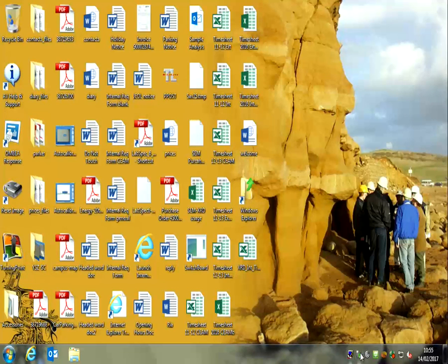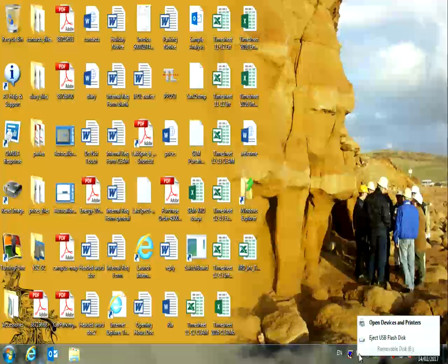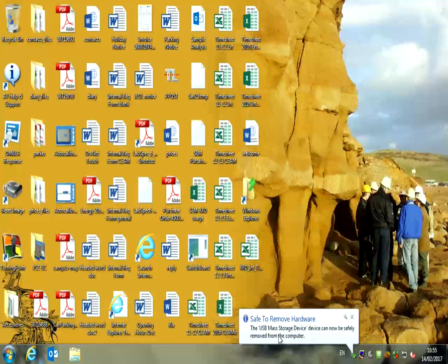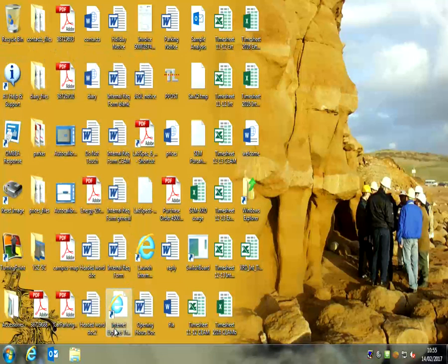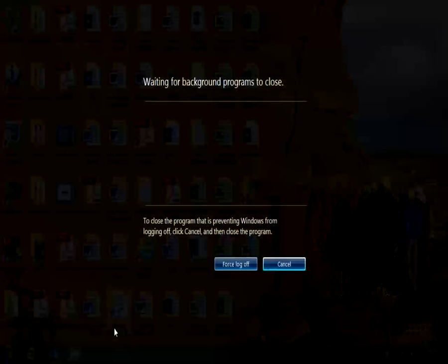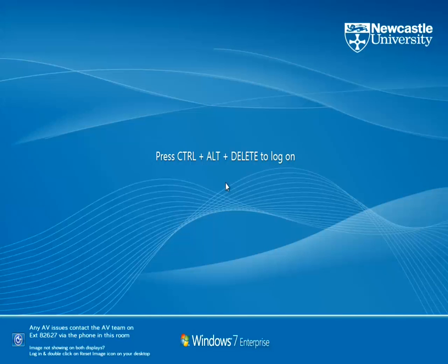Okay, so it's the oxide film rupture mechanism. The root cause is the loss of film because of the stress concentration. The film is mechanically brittle, whereas the metal underneath is ductile. So it will open up if there is a load applied to it, and then the bare metal underneath is exposed to corrosion again. Okay, thank you.